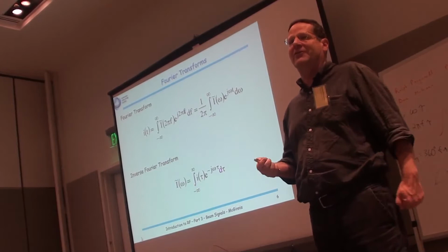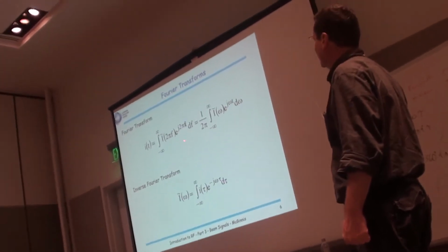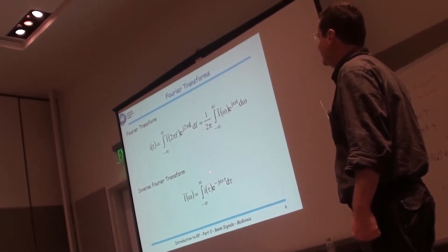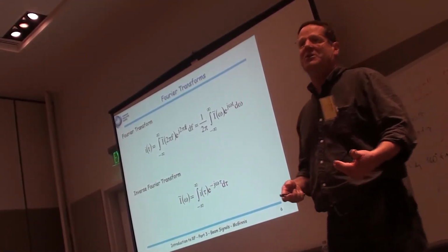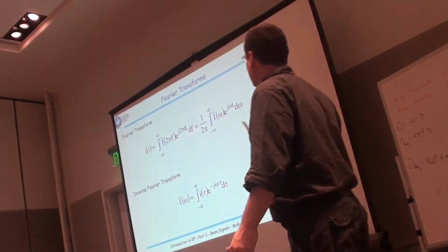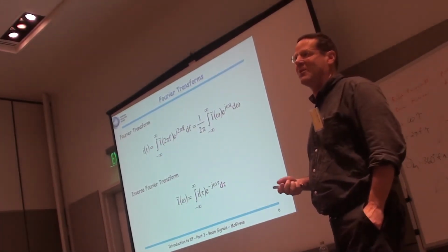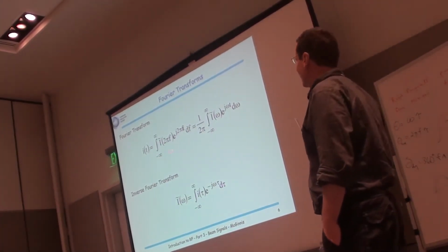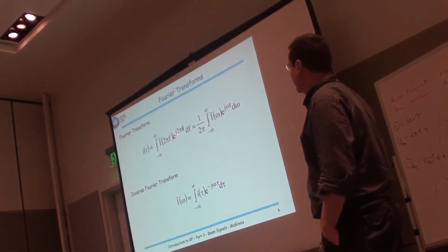As long as you have the round trip, it makes no difference, because here is the inverse Fourier transform and here is the Fourier transform. As long as this sign is opposite that sign, it doesn't make a difference. But the vector signal analyzers that we have in the room assume this sign convention, okay? I don't want to stress this too much, but you have to remember that electrical engineers use e to the j 2 pi f.